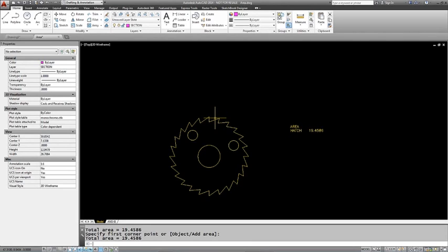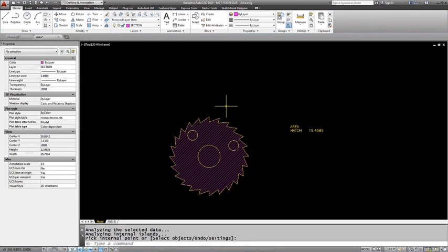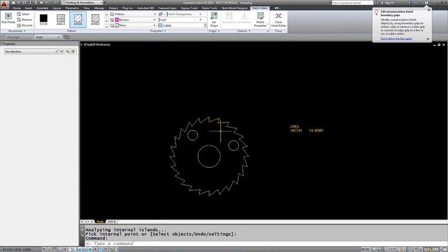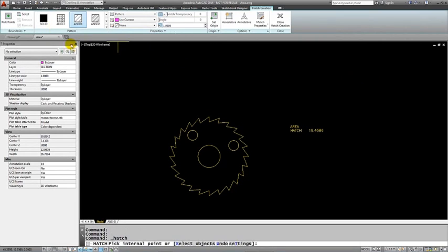My second operation is to apply a hatch pattern. So I'm going to go into hatch. I'm going to select that point inside the boundary, press Enter, and wow, that's terrible. It's not the way it should be done. The islands are not being detected. I know I've got to make some changes. This is really bad CAD, so I'm just going to erase it. I'm just so frustrated. And it says that there are some edits, some non-hatch boundary, non-associative boundaries must be off too. I'm just going to go and start over again.